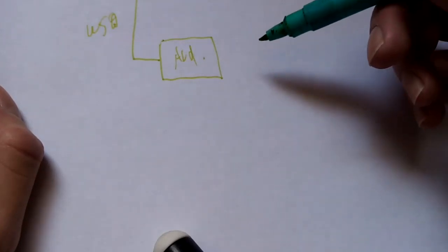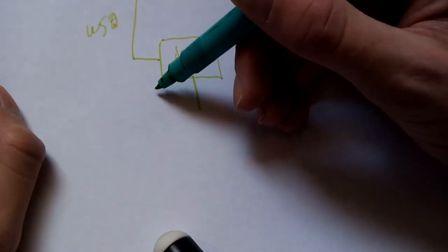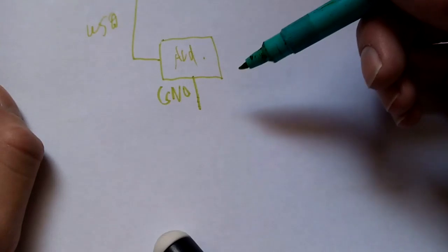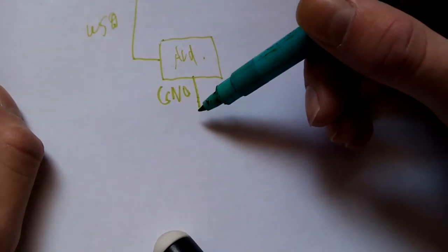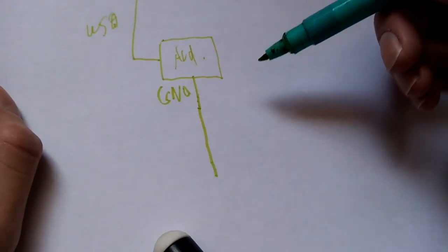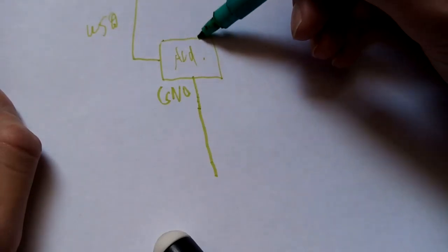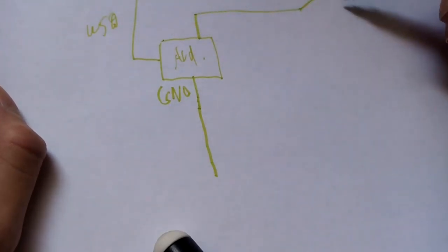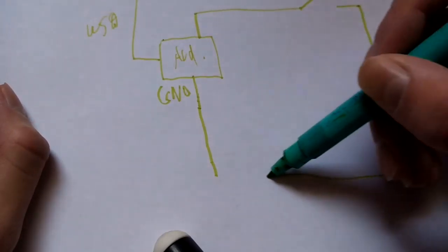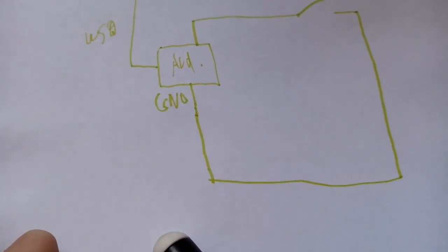And here, I'm just going to use this for one switch. You'll have your ground pin, labeled GND on the Arduino. You'll usually have this connected up to one, depending on the amount of buttons you have. Sometimes you need to use both ground pins, but I'll just use one here. So let's say for pin 2, you'll have a switch, and this will connect right up to the ground pin here.